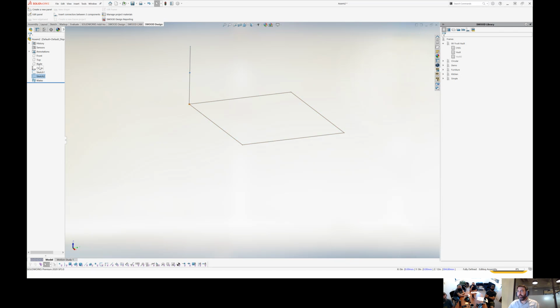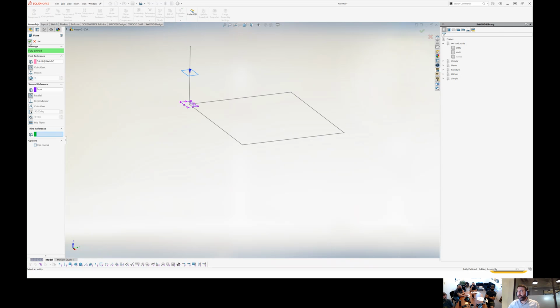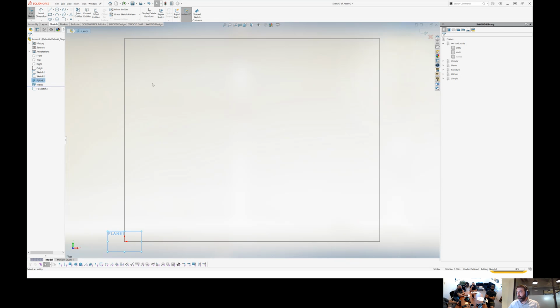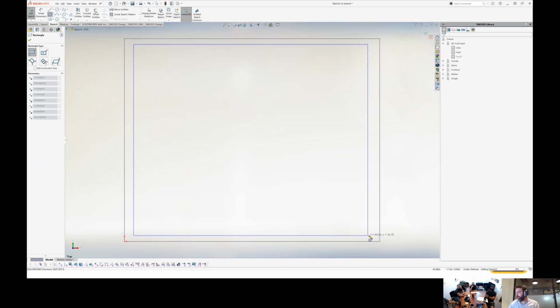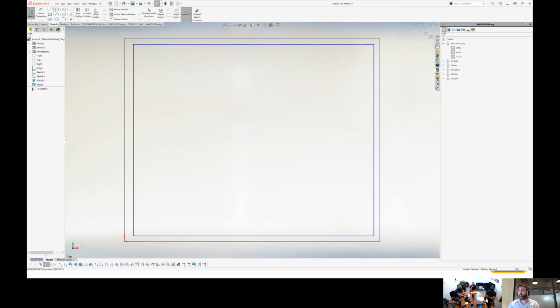And if I want, I can, for example, create here a new plane, and on this plane, create a second level. After that I have a choice: I can make an offset, or I can directly drag another part.